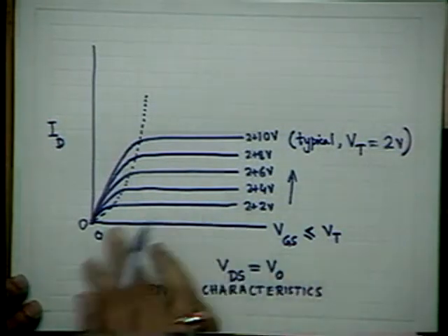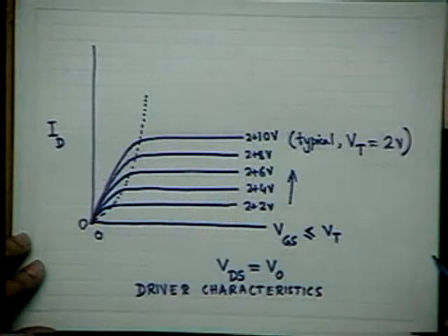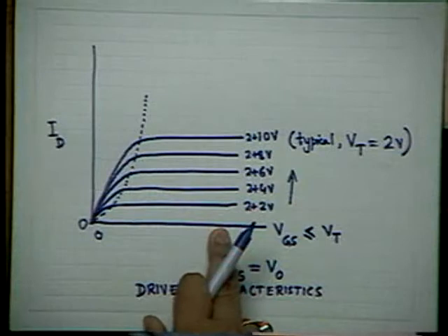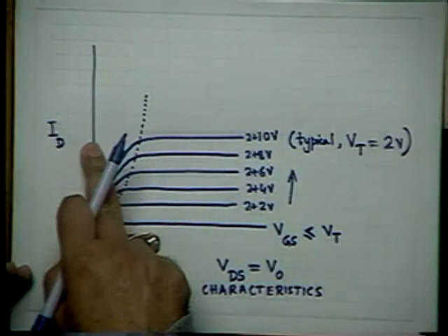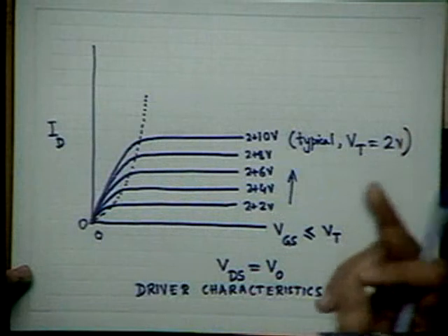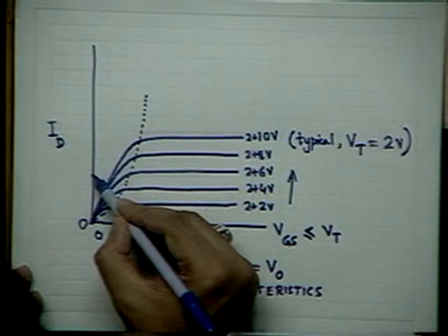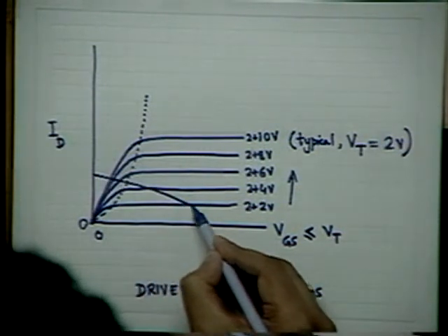And we can superimpose on this set of output characteristics the load line which is offered by the pull-up transistor or the load transistor, which will not be a straight line compared to the resistive load. If you just remember the old things, there is a straight line passing through this point, VCC of the transistor characteristic, and this point, VCC by RC or VCC divided by RE plus RC, whatever. But in this case, I am coming to that, and you will expect to get a curve something like this.